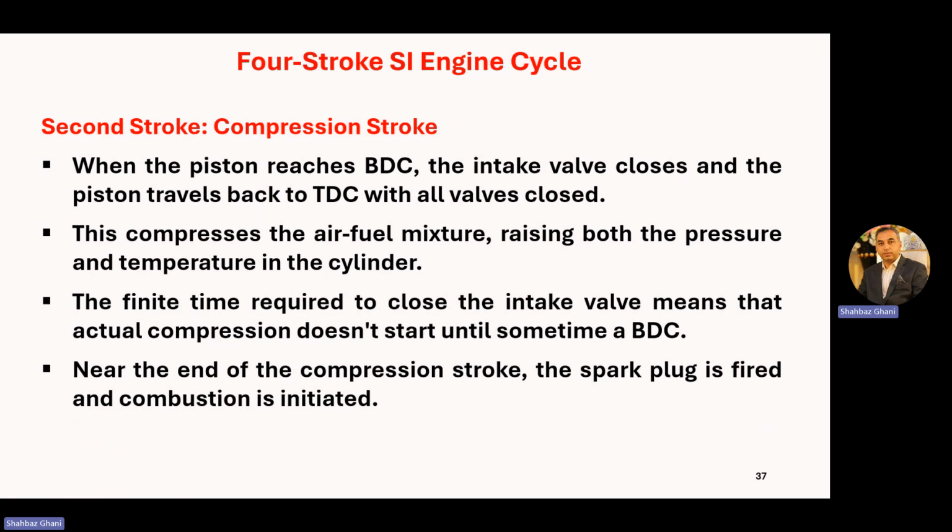Now in second stroke, the compression stroke, piston starts moving from BDC to TDC and intake valves close. This compresses the air fuel mixture, raising both the pressure and temperature in the cylinder. So both valves are closed. Piston is moving from BDC to TDC. It is compressing the air fuel mixture. By compressing the air fuel mixture, we are increasing the pressure and the temperature.